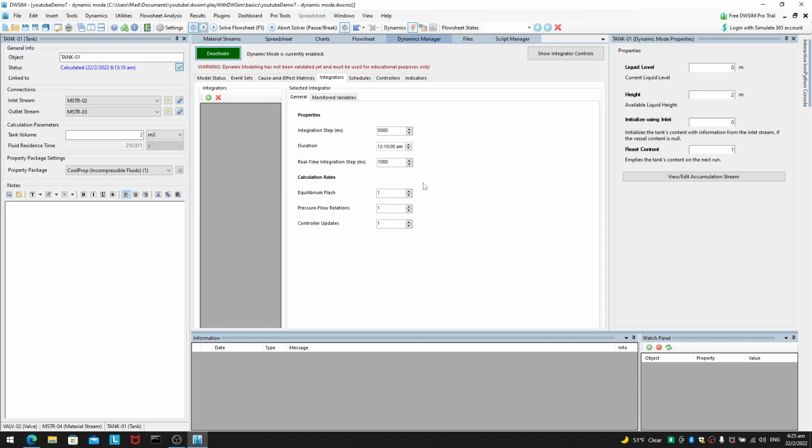And that's how you discretize your equations. Then you will need to decide your delta t, which is your time step. You will need to decide how long you want to integrate it for. And all of these settings you will find under the integrator part. And that's it. So this is the last minimum thing you need.